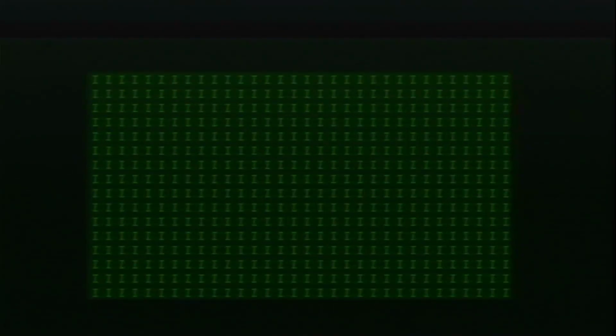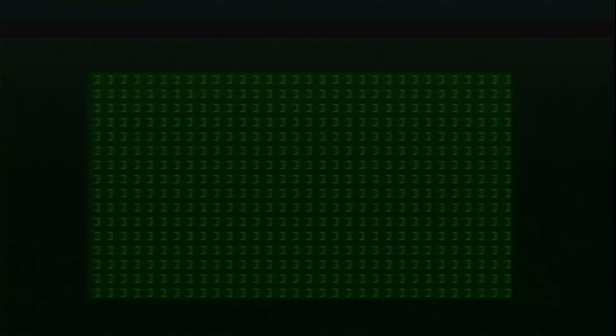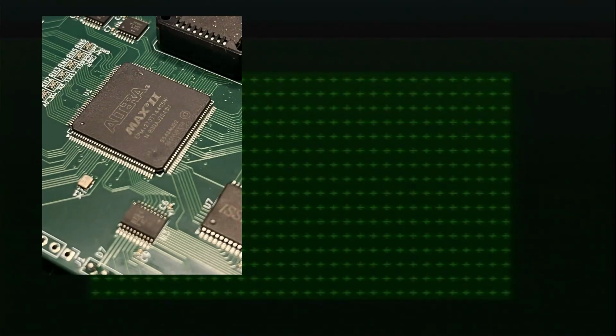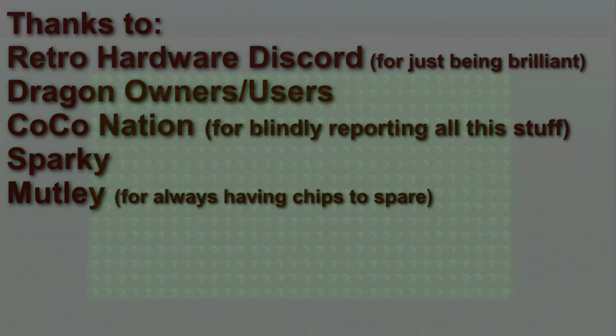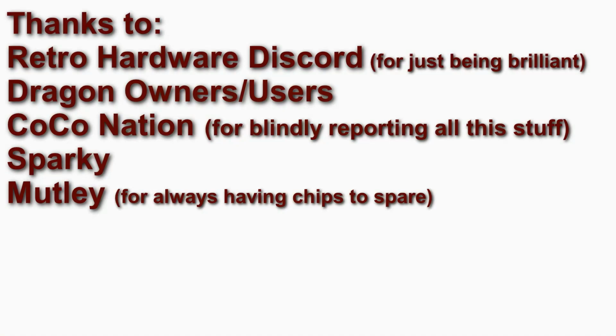The real issue here is that those CPLDs are out of production. Atmel make a plug-in replacement, but even that is end of life. The next realistic option is the Max 2. This comes with substantially more internal resources, which then begs the question, what am I going to do with it all? That, however, will wait for another update.